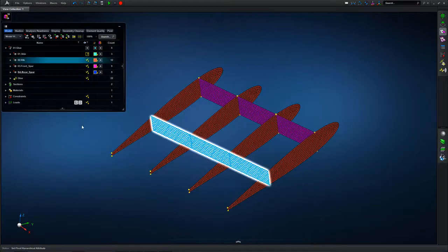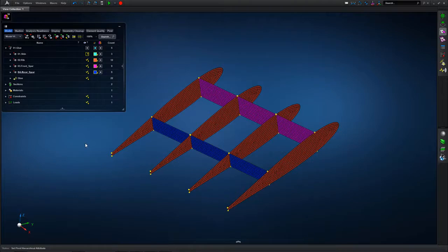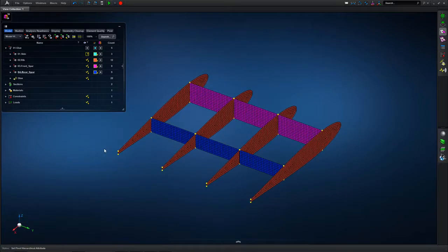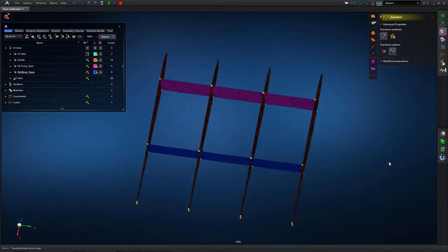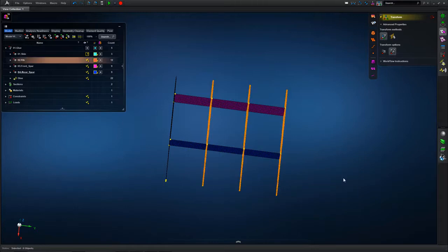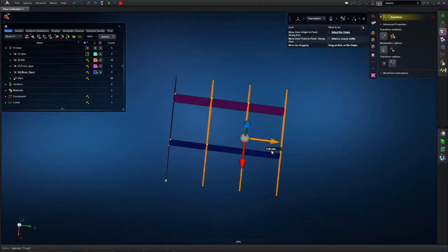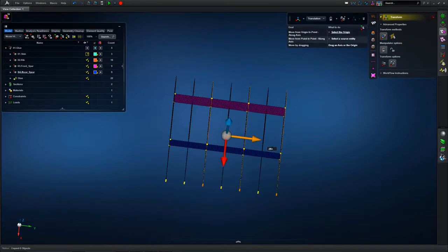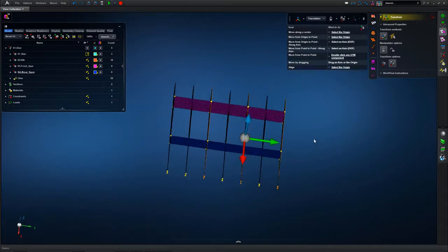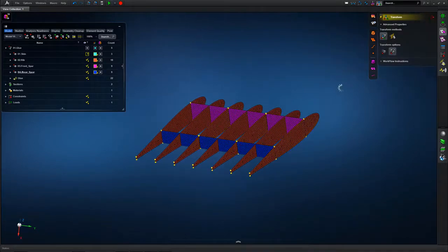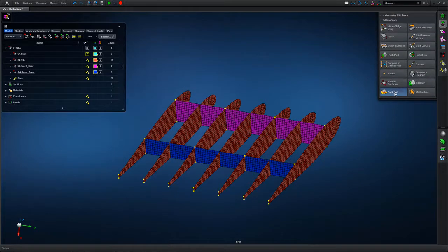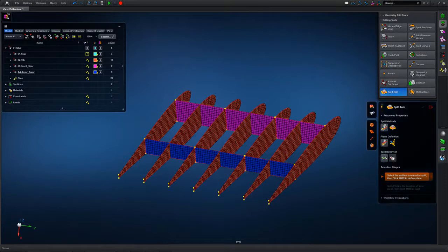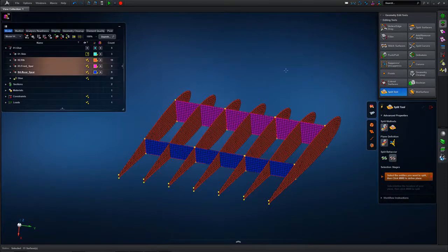So now we're going to look at a layout change, or layout sensitivity. This will involve moving the rib definitions, so we effectively shorten the critical panel dimension. So we're going to simply copy the three outermost ribs by half the bay distance to give us intermediate ribs in that assembly as well. The overall intention here is again to show that because of the meshless nature of Apex, we can quickly tie things or glue things together.